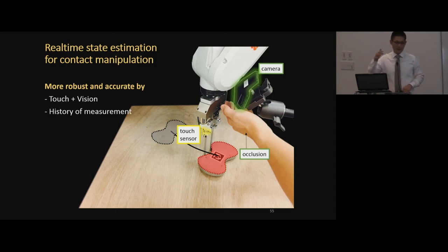In that case, after we know the pose of the object relative to the wall pretty well, we can have a simple way of calculating all the bottom corners of the object and see where they fall. It's just the Vicon cameras looking at the pose, so we can know exactly where the corner is relative to the wall. With that simple technique, we can find out the contact formation. We also use a force sensor to see whether it's making contact or not.